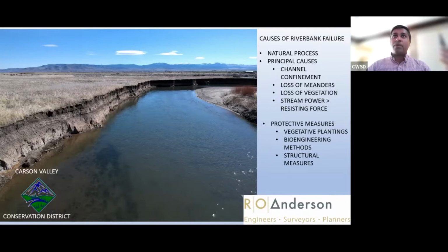And part of the reason, I think Shane mentioned to me, when we started looking into these projects in the early 1950s, the Army Corps engineer went ahead and just straightened some of these reaches of the river. And obviously, if you lose meanders in the river, that's what's going to happen. So the hydraulic energy needs to dissipate somehow, and it will start taking the river banks.